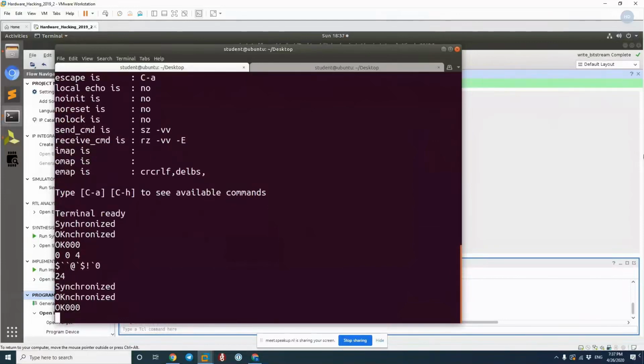And so right now, CRP1 basically enables all the security, but the bootloader, the boot ROM code, is still there. So we can actually communicate with it, debug it, play around with it, etc. Technically, we'd still be able to update the firmware, but we can't read it off of there. So let's pretend this is some super important binary and we actually want to pull it off of this device. So let's try to do it.